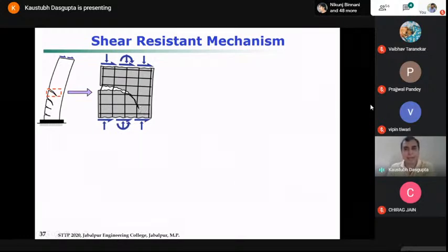So the tip of the crack basically gives you the location of the neutral axis, okay? Zero stress. And then as you can see, the crack width has increased, and towards the tensile end of the section where you have the extreme tensile stress, your portion of the bar also has become unbonded with the concrete.